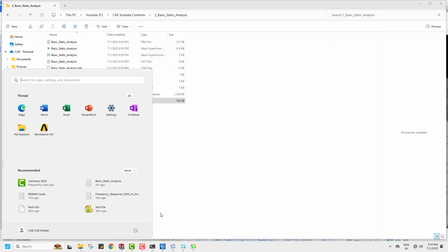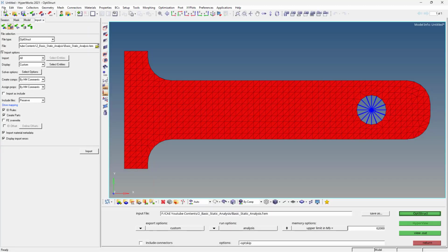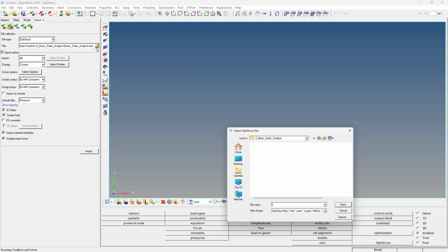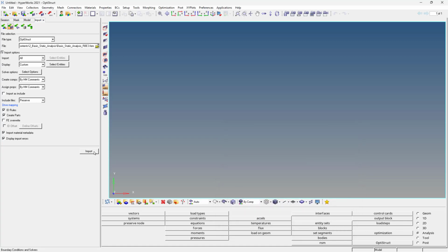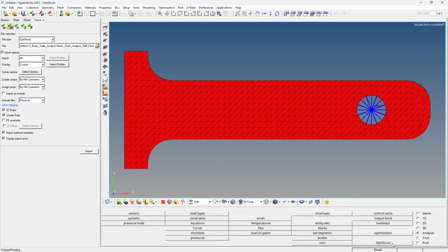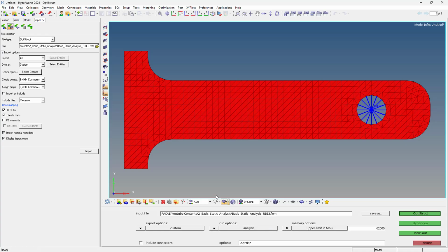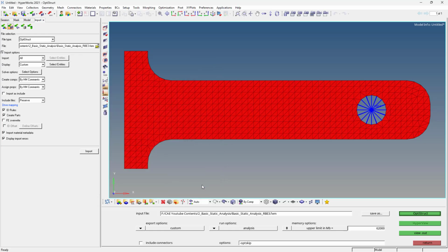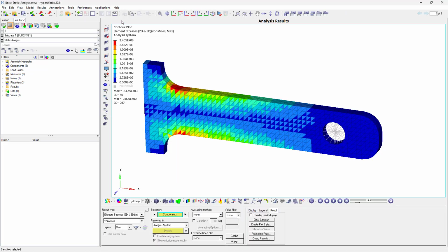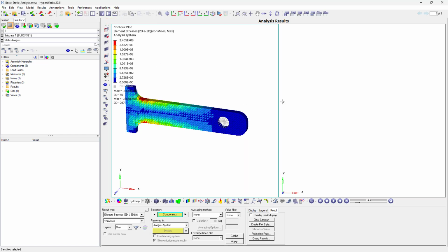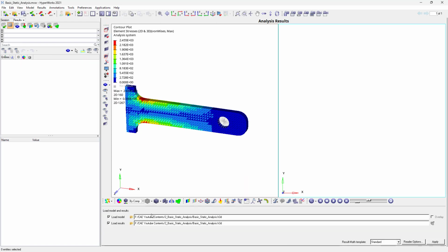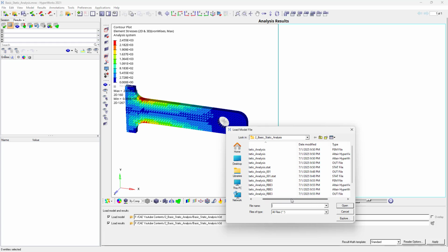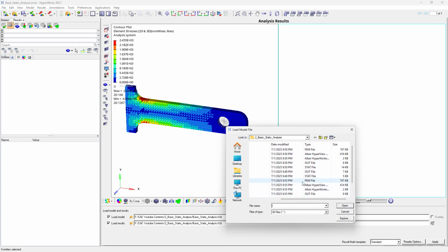Now go to HyperMesh, just load it once, open the new session, very important. Just import, click on analysis of struct, replace the model and just run it. Now don't open the result here, just quickly go to the previously opened HyperView, open this new panel here, click on open and then select the RBE3 H3D file, this one.